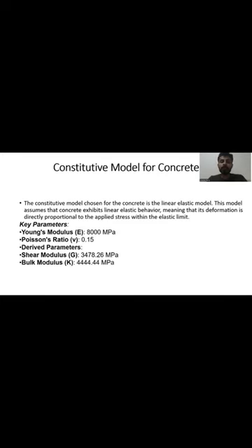concrete foundation is modeled with the Young's modulus of 8,000 megapascal and a Poisson ratio of 0.15, and the surrounding soil, a highly resilient clay, is characterized using a linear elastic perfectly plastic model with specified parameters, which our group has been assigned: 21,000 kilopascal and 85 kilopascal respectively.